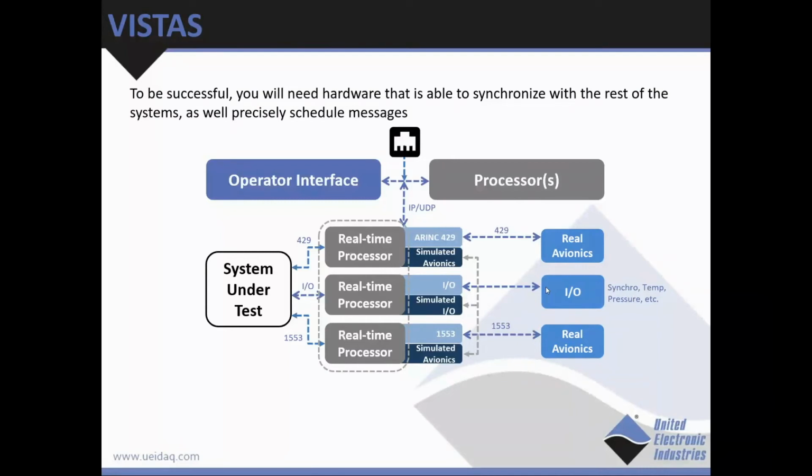So now I'd like to introduce a concept called VISTAS. The idea of VISTAS is to create a protocol for testing avionics systems. Very often, a particular avionics device can't be tested alone. It requires other parts of the avionics suite to be present and deliver information, hence the iron bird. To accomplish that, VISTAS allows easy substitution of missing parts to be emulated using hardware such as UEI's Avionics Interfaces.